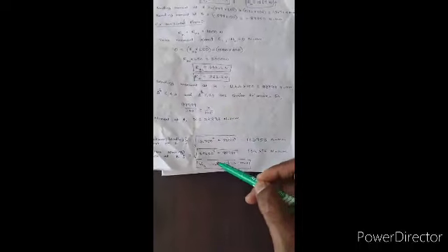So that's what I have written here. If you find the root, at point A the value is 140753, at point B the value is 134435. Whichever is the highest, you take that as the bending moment. Comparing both, the bending moment at A is higher, so I am taking that as MB.